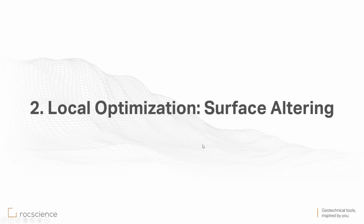So that's global optimization. Say we run particle swarm or cuckoo search and we get our global minimum surface. Now we can make it even better using a local optimizer. This is applied after the first global surface is found. And our famous local optimizer is called surface altering, which was actually developed at Rocscience.